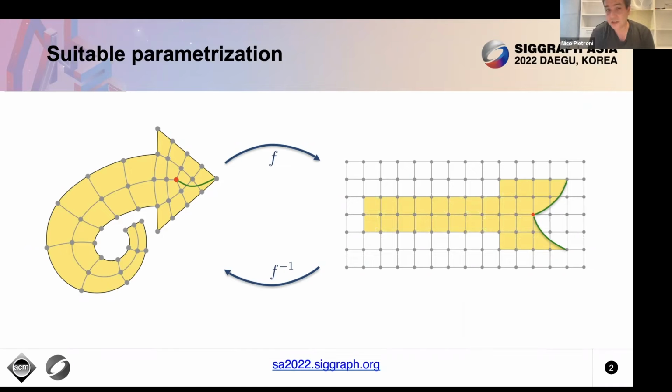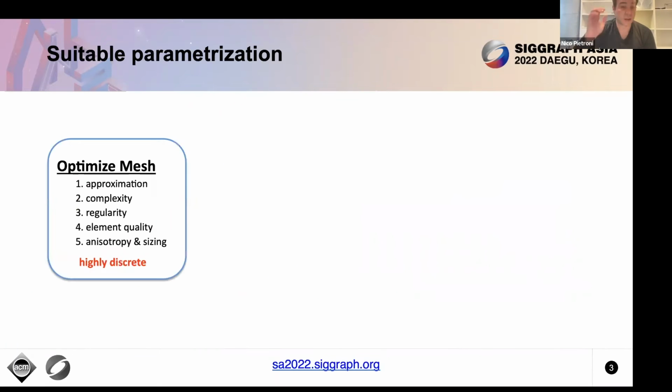A similar idea works for volume meshes. You have this mapping, and obviously you can also have discontinuities, and this is especially true when you have singularities, like here in this case, where you have this valence three vertex. This works more or less the same in a volumetric mesh, but the trick is that you need to have a transition along singularities with some integer number of 90 degree rotations and certain constraints. I don't want to go too much into detail, such that when this parameterization is assembled back to 3D, or to the space of the real mesh, the tessellation will be smooth and continuous. So you have smooth parametric lines varying from one to the other.